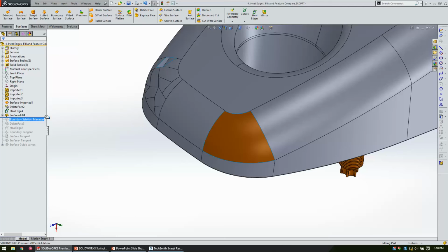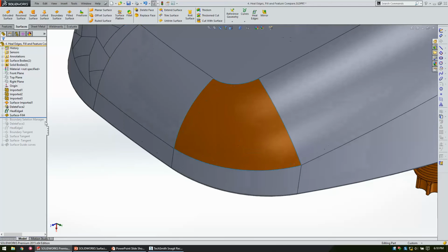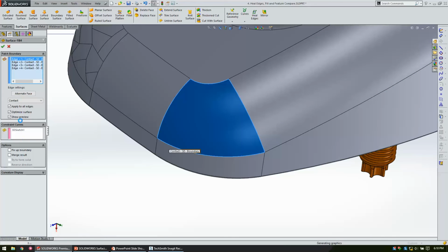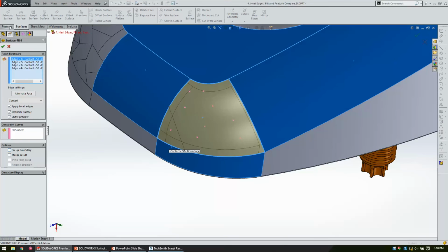I don't have it here evidently. But where I do this and I overlay all the faces on top of each other, if you just do a boundary face or a surface fill without those constraint points, it's several thousandths off. And if you do the constraint points, it's just exactly right on. So that would be my most significant tip that has saved me the most hassle throughout my design career, of the 3D points in space doing your constraints.